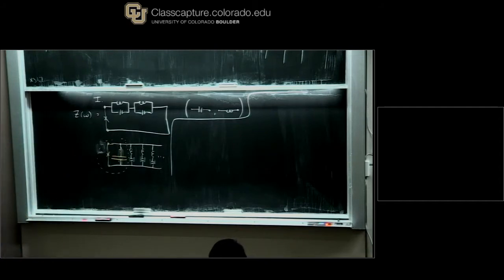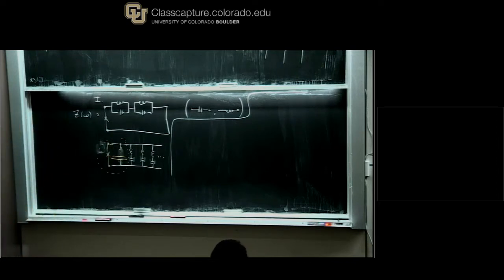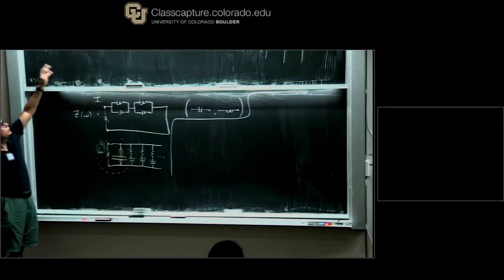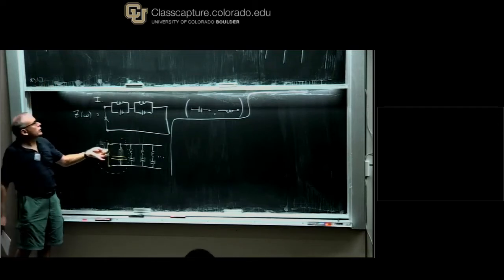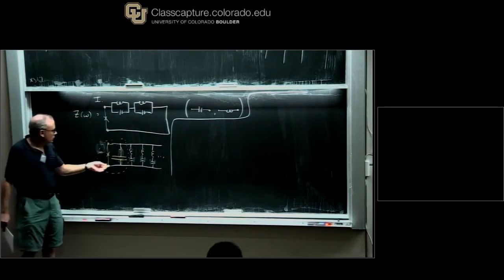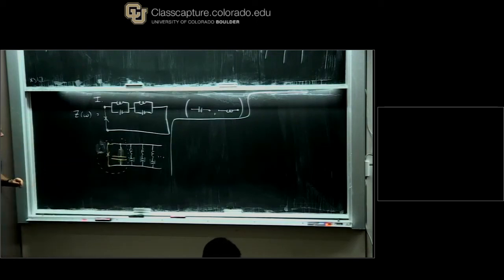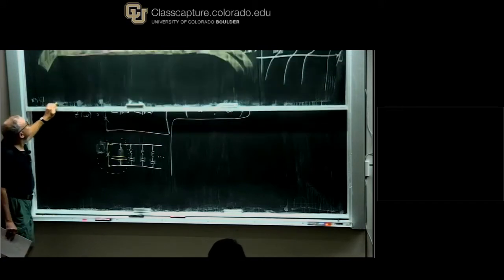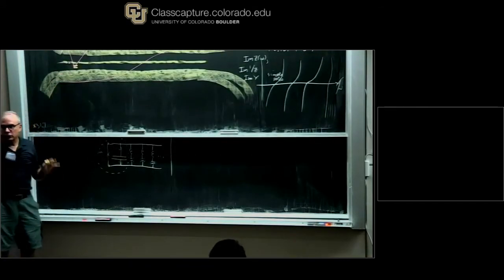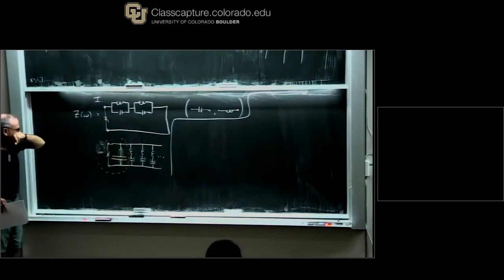So it is indeed a fair approximation to not put it in, but it has a unique value. That is, for any given metal structure, you can calculate. You determine your analytic function, you fit it, or you decompose it into poles. You find a pole that corresponds to this, and so there's no ambiguity about these parameters. However, this capacitance may not really be exactly the geometric capacitance of this exact structure in isolation, but that's fine. It's sort of a potentially renormalized value.